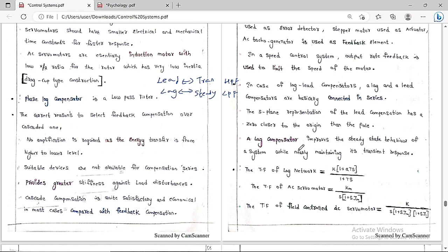There is a deviation to an extent, but in terms of approximation, it maintains its transient response. So always remember, any compensator, if it improves one thing, is going to degrade the other thing to a smaller extent. You will always have to keep this in mind.